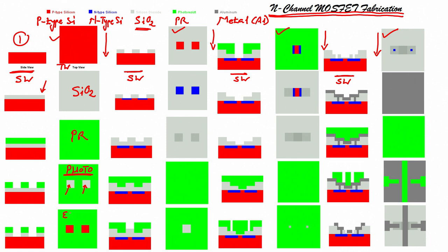So, here we have etched silicon dioxide. So, you can see here silicon, right, what you can see here is silicon, here and here. Why? Because we have etched the silicon dioxide. How we can etch the silicon dioxide? I had told you, we can use buffer hydrofluoric acid, right. Until here is okay, easy.